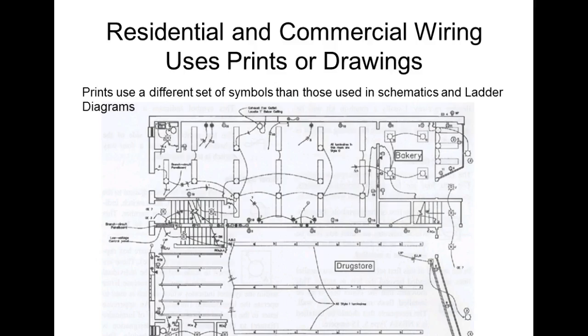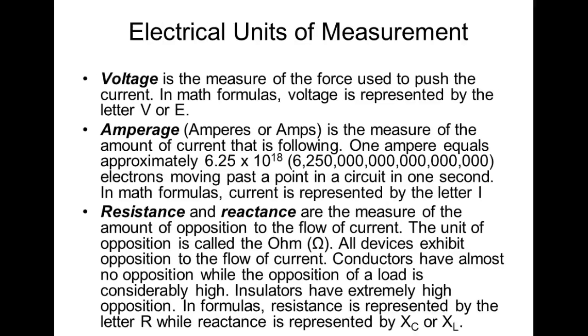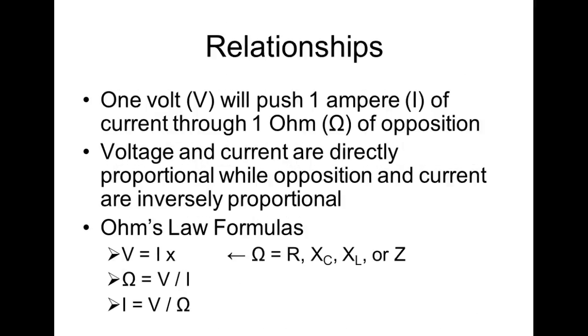We looked at some prints for house wiring. Talked about voltage, amperes, and resistance and reactance. Reactance and resistance are a little different, and we're going into communication cables, not power cables. And that's not really true. Engineers have to worry about reactance even in power cables. But it's extremely important to understand reactance in communication cables.